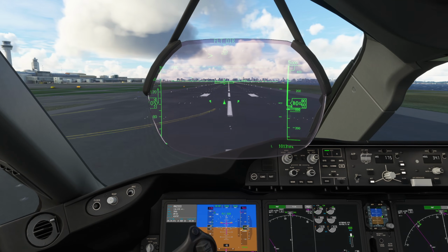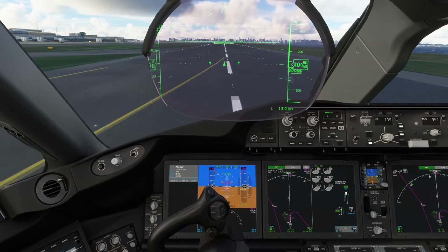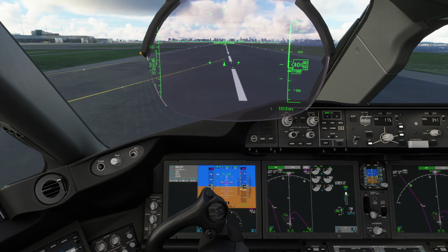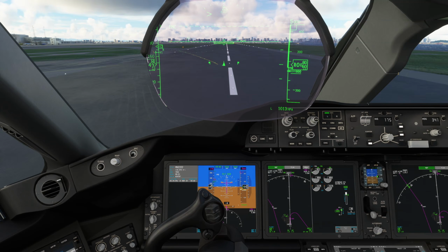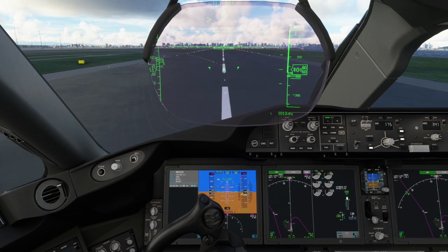so I'm having to move more and more of that aileron in. Through 80 knots, I should have released the yoke, or released the forward pressure, but look how much aileron that's needing, and that's maybe about the most you'd ever need. As you accelerate, that'll reduce because you'll get more control over the wings through the airspeed. So into an aileron, I'm using left rudder down there to keep us on the runway.